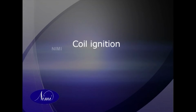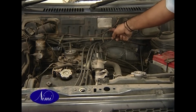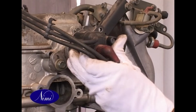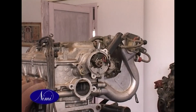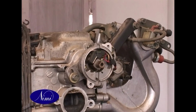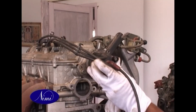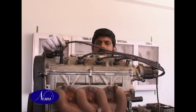Coil ignition. The main parts are the ignition coil, which transforms the battery voltage from 12 volts to that required to produce a spark at the plug. Contact breaker. A mechanically operated switch breaks a low voltage circuit and causes the coil to produce a high voltage current. The timing of the spark is controlled by the contact breaker. Distributor. Fitted to multi-cylinder engines, this unit distributes the high voltage current to the appropriate sparking plug.